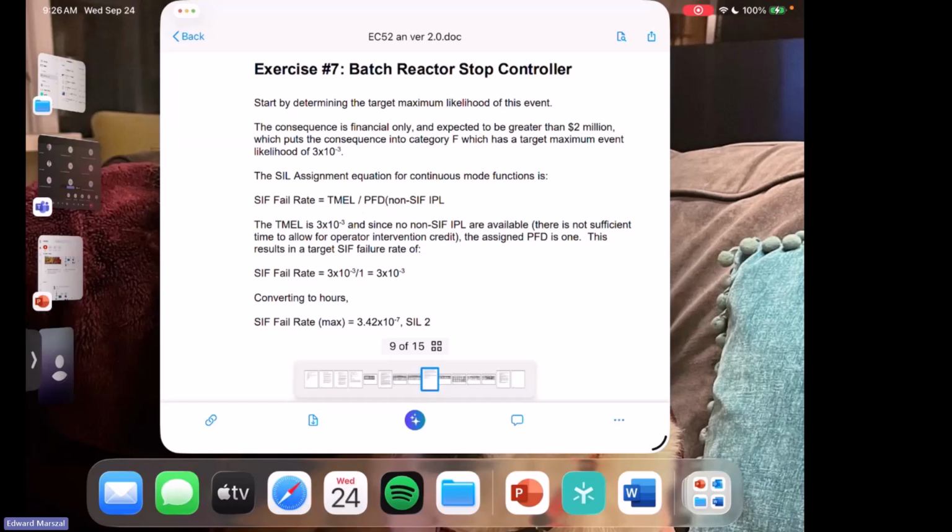But before I get to that, what did we actually do for this plant? We had them change their basic process control. So instead of ending the batch when you get a high oxygen alarm, we totalized the flow of air going into the reactor, compared that against the weight of the reactor, and basically when the totalized flow of air has consumed 95% of the reactants, we just stop the reaction. So we are not relying on that oxygen analyzer to be our control.